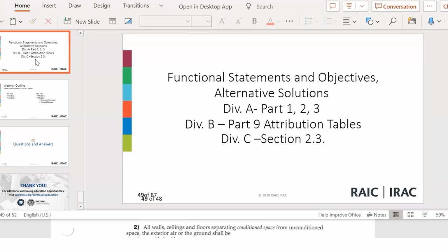What else? I would use the templates. My approach is always to use the matrix, start from there, but know if the use of sprinklers is a possibility, and know what kind of construction you're going to be using. If he wants to use non-combustible construction in accordance with the code, then you want to put limitations on what kind of products you're going to be using in your building. If you're using combustible construction, there's more flexibility in terms of what materials you choose and specify. Okay, thank you. Yeah.